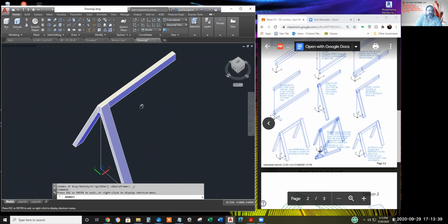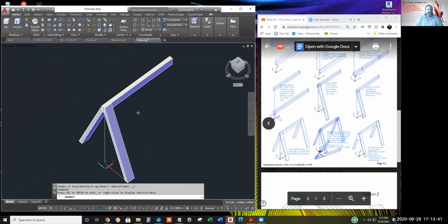I'll admit, I think I tend to use the 2D mirror command when it works, rather than specifying 3 points for the mirror plane, or as Dan pointed out, ZX enter, specify 1 point.